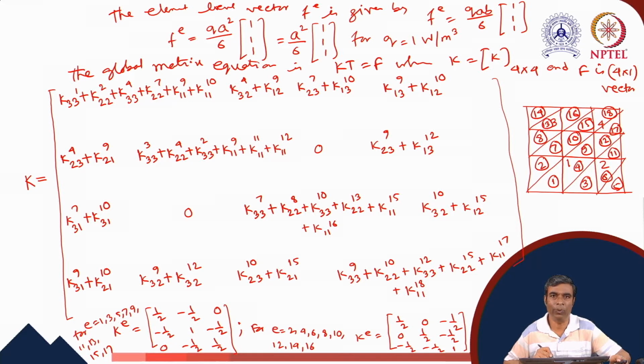So easily we can understand that the element level matrices that we have written here are linearly dependent, because when we calculate these matrices, we take the derivatives of shape functions that certainly lead to linearly dependent matrices at the element level, and when we perform the assembly and implement the boundary condition, we finally get a linearly independent global matrix equation system. Now we can substitute these values.